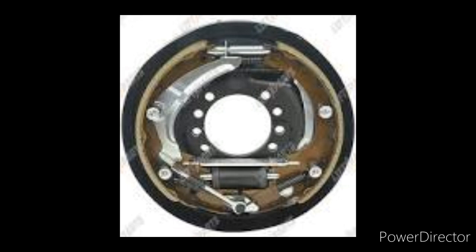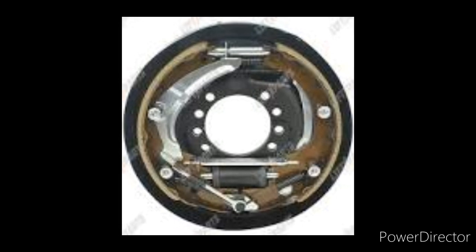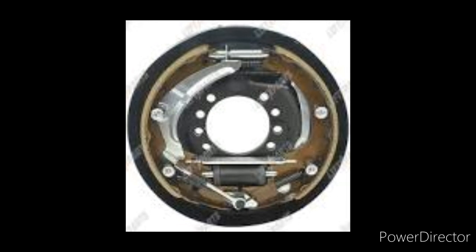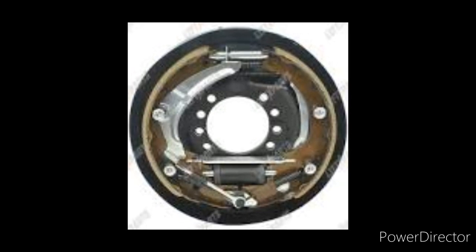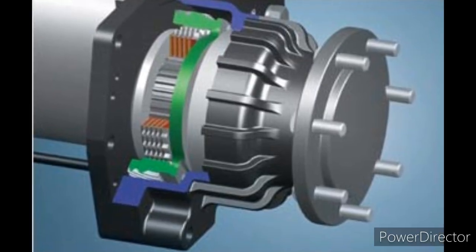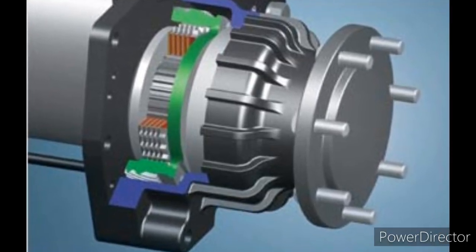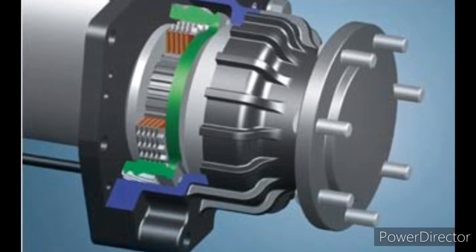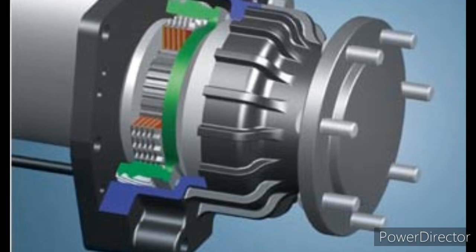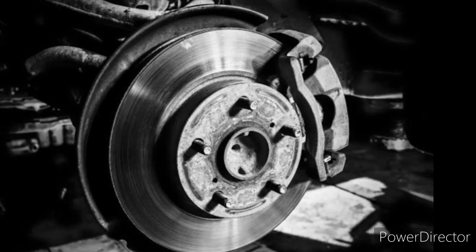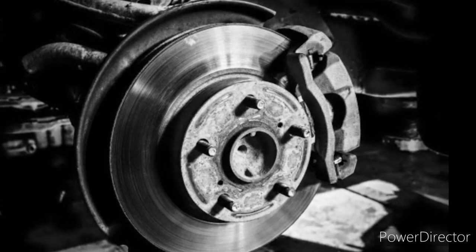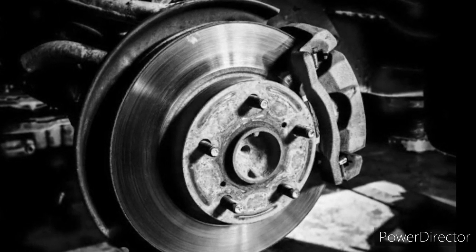Forklift brakes. Parking brake. This brake is operator controlled and locks the drive wheels by not allowing the other transmission components to rotate. Service brake. There are several braking systems available on forklifts. Most brake systems are actuated by hydraulic pressure supplied by a master brake cylinder located at the brake pedal. Some trucks have a vacuum or hydraulic power assist system that reduces pedal effort. Air brakes are common on large trucks.